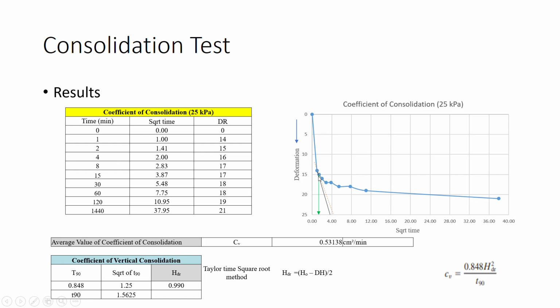Here we need to draw a line from the start of the curve, then we transfer that point to around 1.15 by multiplying with it, then you need to extend it back, so the point where it touches that black line, you need to extend back.